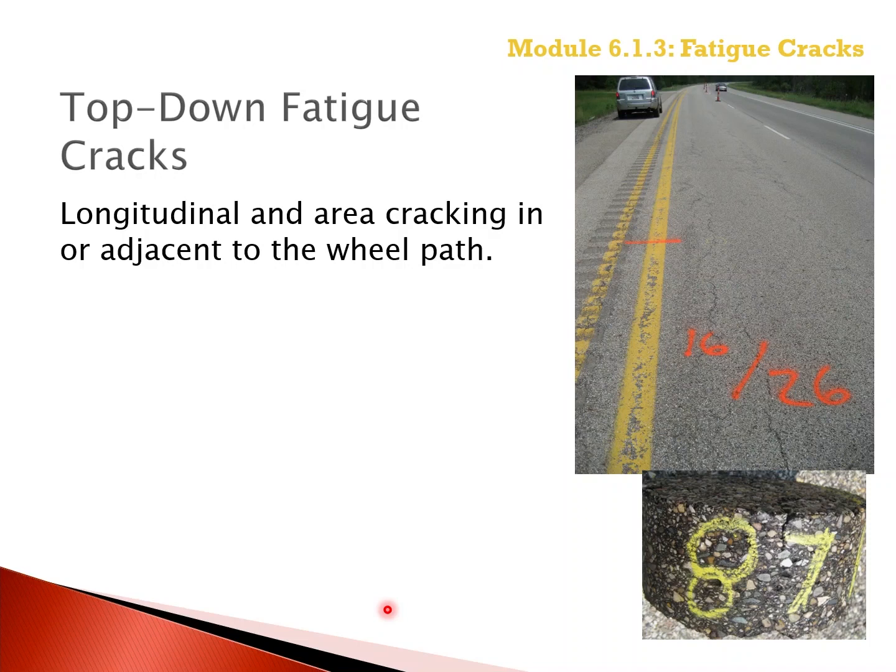Longitudinal cracks start as short longitudinal cracks and then interconnect to form the classical alligator cracking pattern as previously defined. Longitudinal cracks are converted to an area basis by multiplying the total length of longitudinal cracks by 1 foot width.